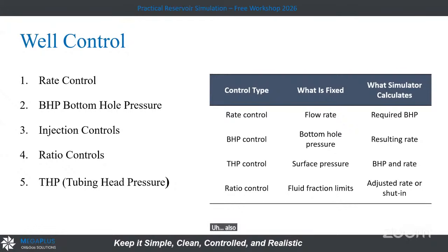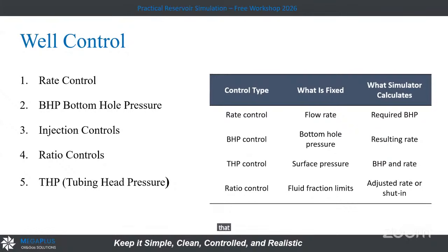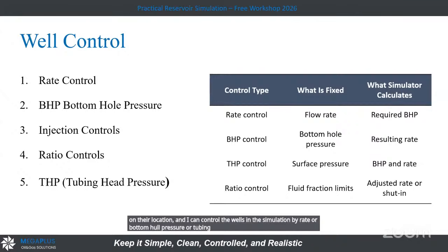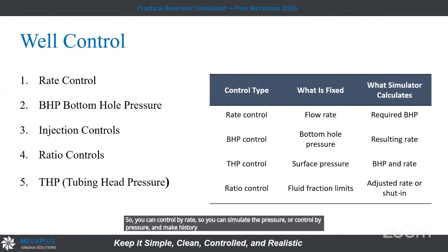Also the upscaling and the LGR. And before I go to a case study, the last thing in the reservoir simulation is well control. I have to put the wells in their locations, and I can control the wells in the simulation by rate, bottom hole pressure, or tubing head pressure, or wellhead pressure. So you can control by rate and simulate the pressure, or control by pressure and make the history match by rate. It goes that way.